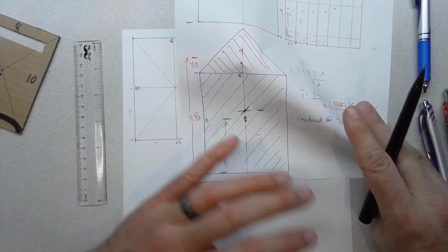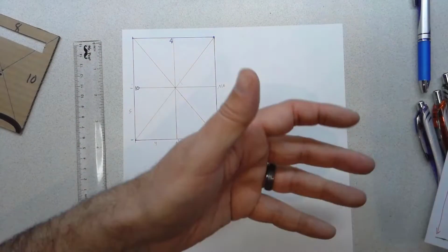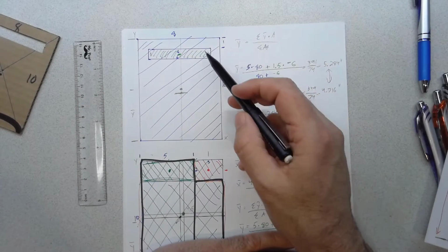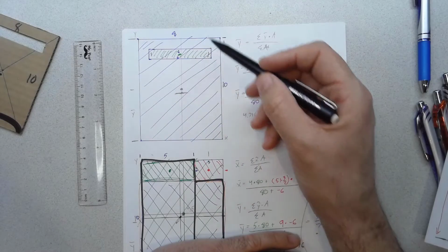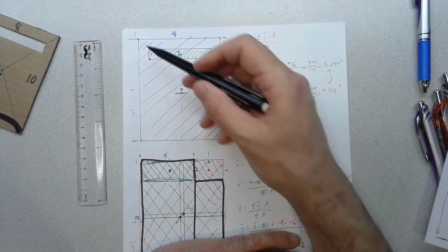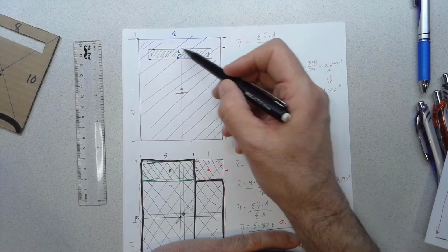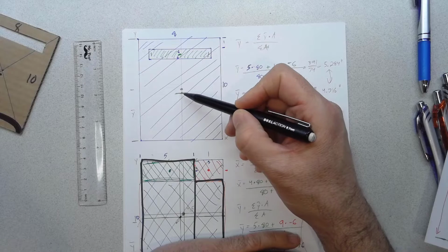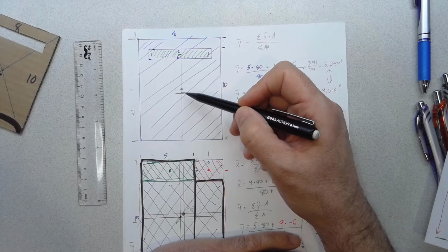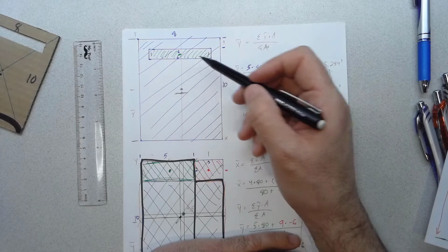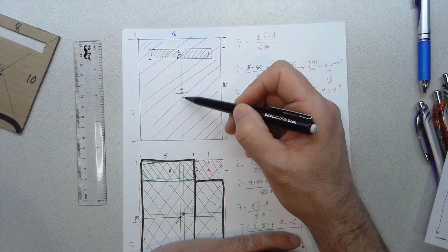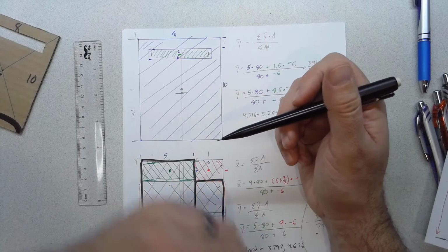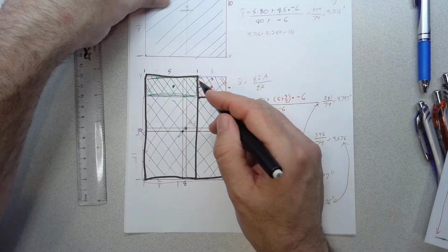We also looked at other shapes where we subtracted some pieces to make a composite shape and found a centroid. So here again, if we look at the original rectangle, centroid's right at the center of the axis of symmetry. But then if we took out this rectangle up here on the top, then we're going to have to shift the centroid down a little bit, because now we're going to need to offset the weight that we've taken away here by moving a little bit this direction. So some of what used to be on this side of the centroid is now on that side, so it's all equal. And then lastly, we did a similar thing by taking a corner out.